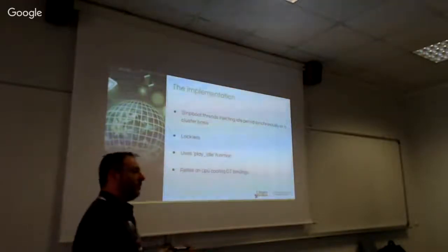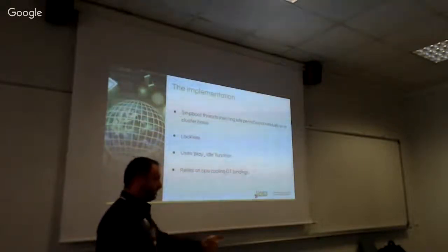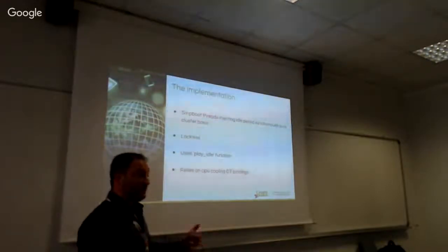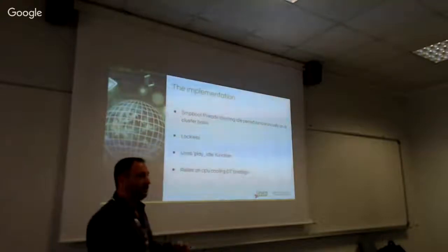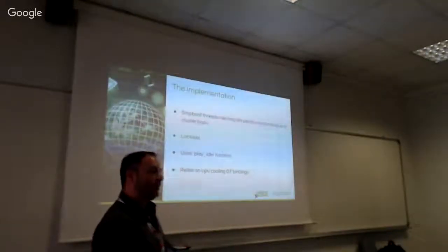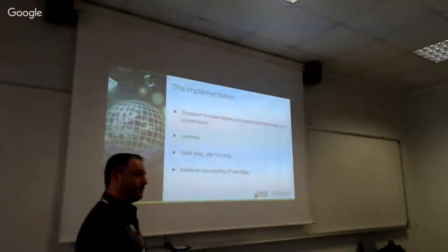The idea is to give them a lot of options, and then choose the right one. Just to experiment and choose the right idle duration. Choose if the cpufreq cooling device is better than doing idle injection. It might be able to dynamically figure it out. It might depend on the workload, because if there is some real-time workload, for example, you're streaming audio and you need to limit the exit latency and thereby limit the available idle states, idle injection might not be effective anymore.